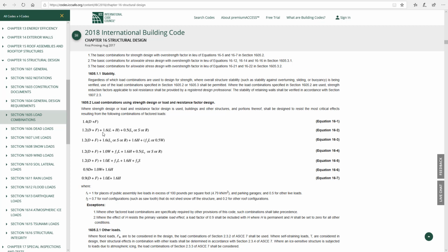It's also important to note, as I said in the previous video, that the dead load only gets an increase of 20% because we're pretty confident about the assembly for the dead load. However, snow load and maintenance worker load is pretty unpredictable throughout the entire life of a building, and so we increase those loads by 60%.